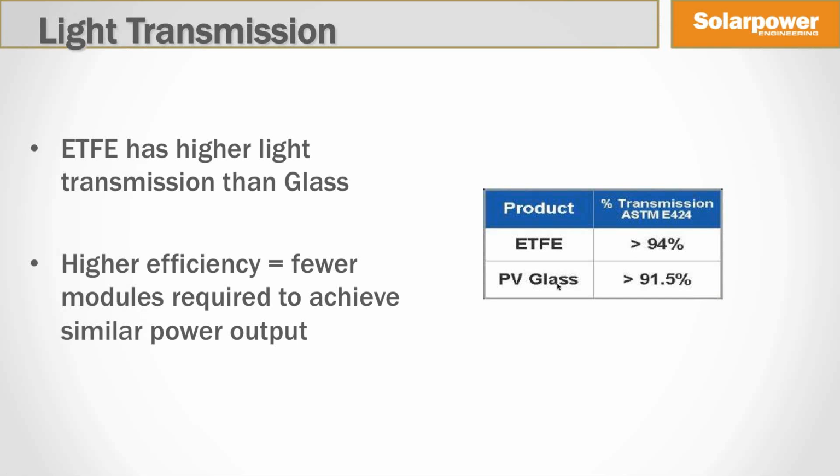The advantage that crystalline silicon technology brings to the table is the high conversion efficiencies compared to other PV technologies being offered there, typically in the range of 14 to 17% at the module level. It also brings proven high volume manufacturing processes into the game.